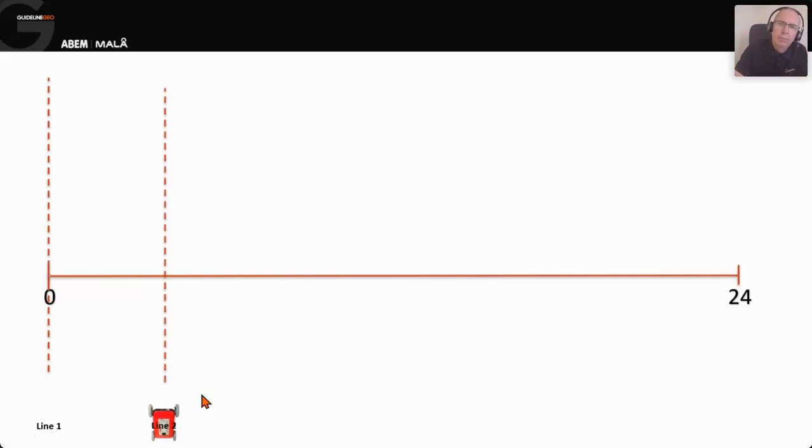And then you stop the profile. Move over again, again 1 meter. You can increase that if you want. If you need to, you can go to 2, 5, 10 meters, whatever. We're just going to input that data again when we come to the baseline crossing screen. But I'm keeping it continuous here.